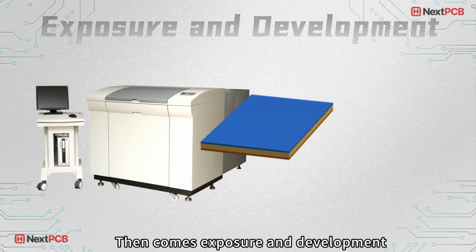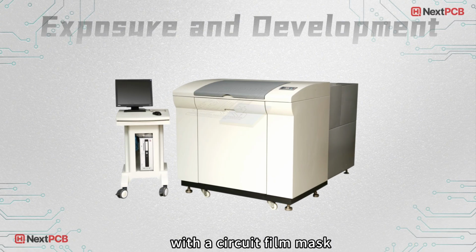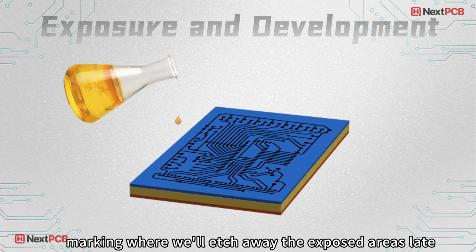Then comes exposure and development. The PCB board goes into an exposure machine with a circuit film mask. UV light shines through the mask onto the blue film, marking where we'll etch away the exposed areas later.